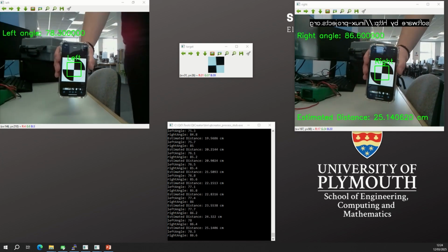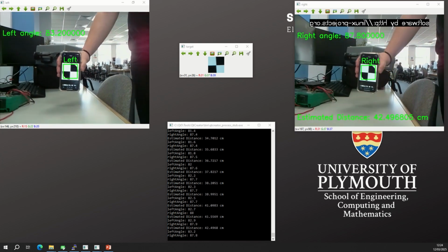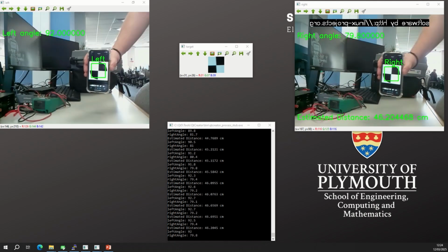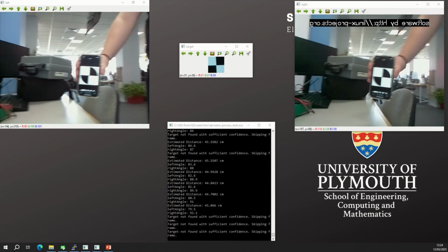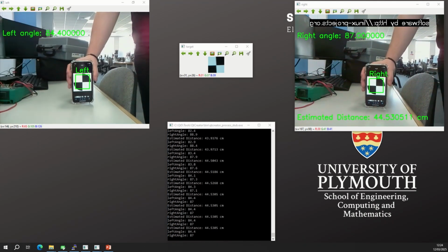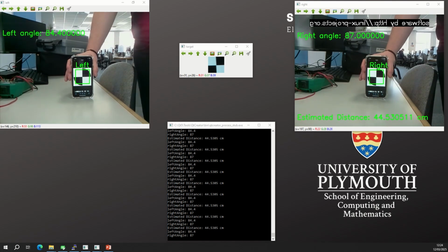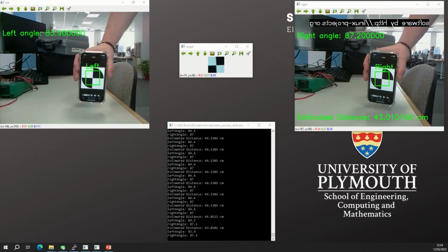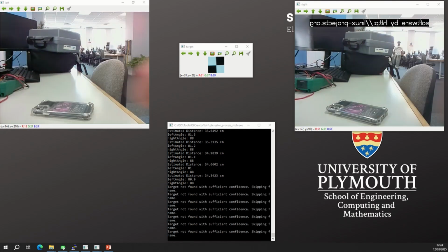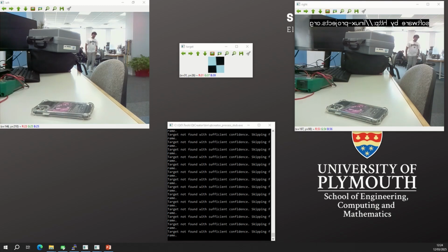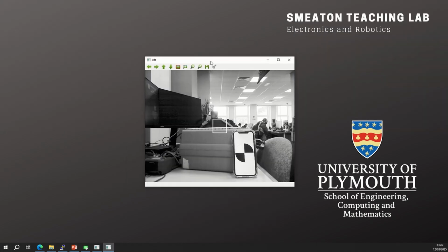But it does continue to recognize the image at both close and far away distances, and is still able to estimate the distance effectively, proving that we do have a working product, and it is very user-friendly. But due to lens distortion, it isn't always having that successful tracking and sometimes loses focus. To fix this issue, I converted the feed to grayscale.